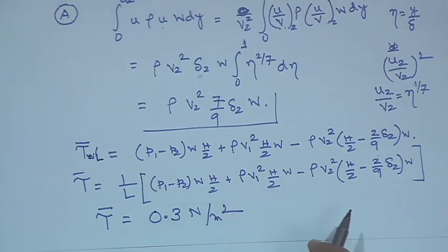So, an important point in this specific problem is that you are finding out the average value of the wall shear stress, not the point value of wall shear stress. So, you may ask that I have a profile at location 2 which follows the 1/7 power law, so why not differentiate the profile at 2, multiply it with mu and obtain the value of the shear stress?